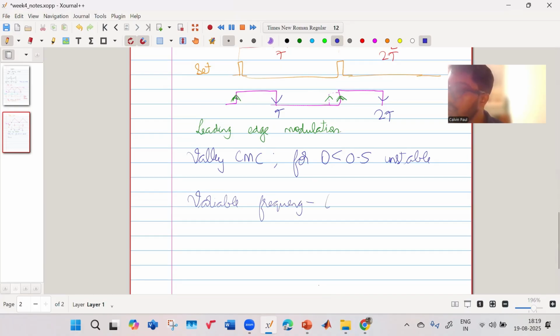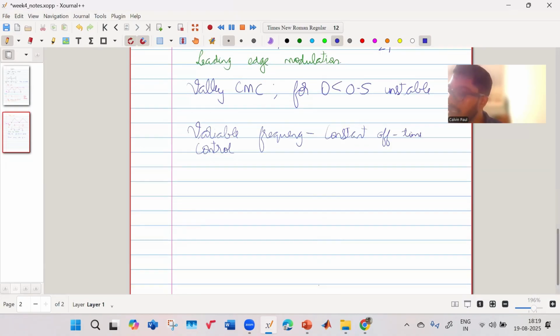which is your constant off time control. In constant off time control, again you have your peak reference. This is your I peak reference. Assume your current signal touches over here. Then it will be off for one fixed time.